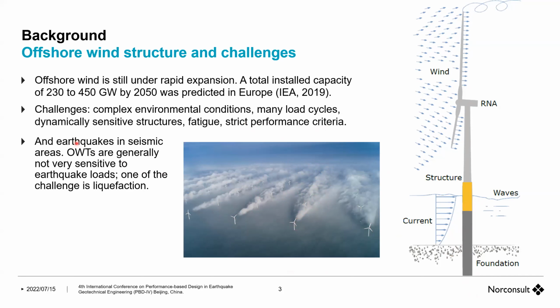But of course, for us, earthquake in seismic areas, very generally speaking, offshore wind turbines are not sensitive to earthquake shaking per se. However, it's a very general statement. One of the challenges is liquefaction, and the reason is that the natural period of these structures is typically 3 to 4 seconds, and earthquake is not the number one concern.